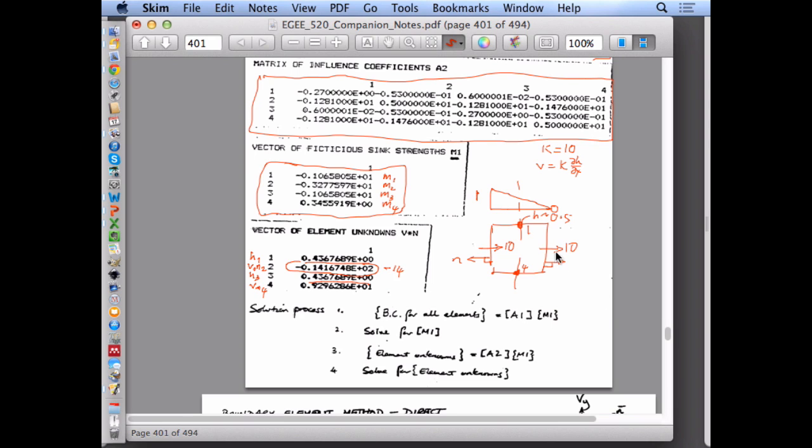And the value out here is in the same direction, and this is plus 9.3. That's not great. And so that's it. So the results aren't quite right. Why do you think the results aren't quite right? Yeah, discretization. Bad discretization. So that's it.